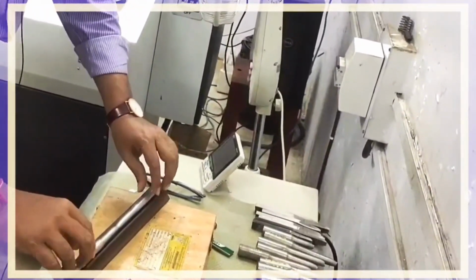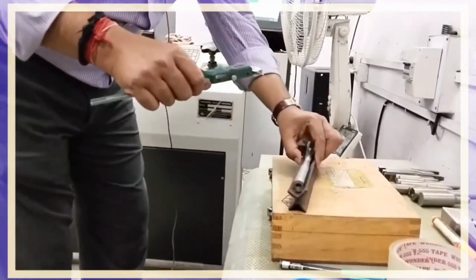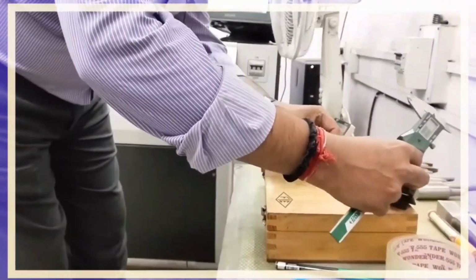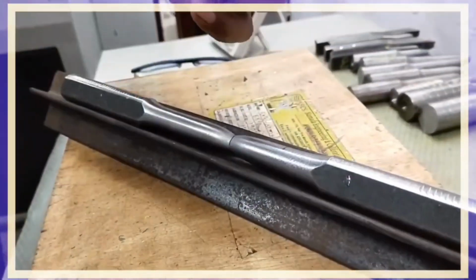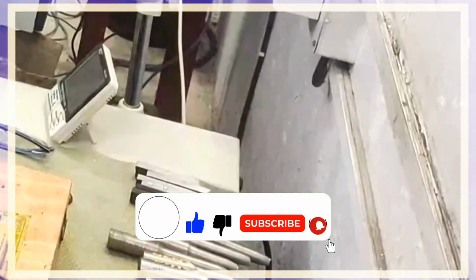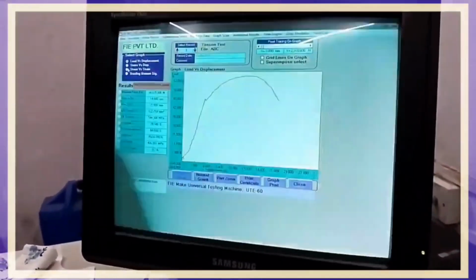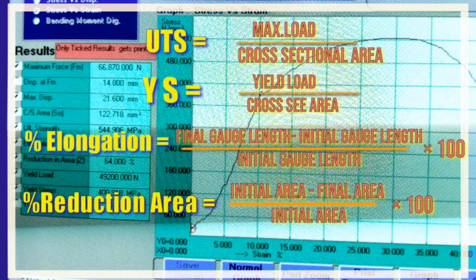Now we will feed the final gauge length to the system. The final gauge length is 64.42 millimeters. We will measure the final diameter for the reduction of area. We will measure the final diameter for the breaking area. The initial diameter was 12.50 millimeters and the final diameter is 7.50 millimeters. Now we will close the machine and save the result.